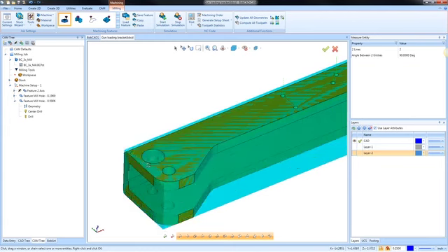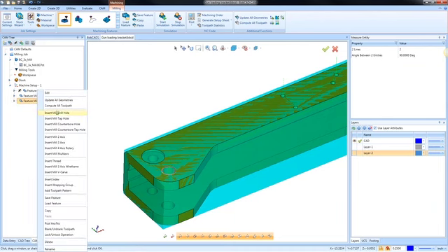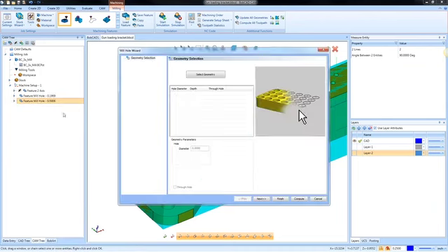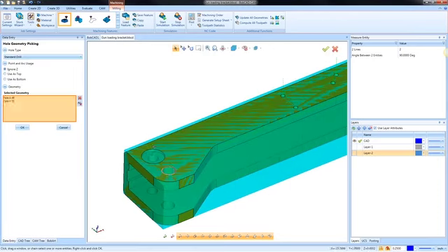This one over here I want to address because you can see that it doesn't start at the same Z height, but we would still need to drill it from there. We'd probably drill the hole first and then do the counter bore. So how do we adjust that? We're going to do drill hole, select geometry, and pick the cylindrical face.